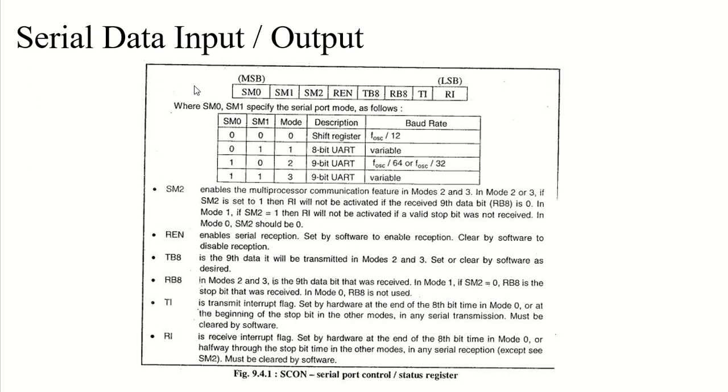Physically, one of them is write only and is used to hold the data that is to be transmitted out from the microcontroller via the TXD pin, while the other one is read only and will hold the data that is received from the external source via the RxD pin.